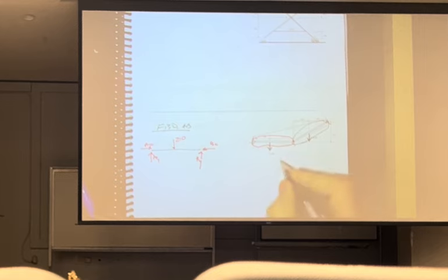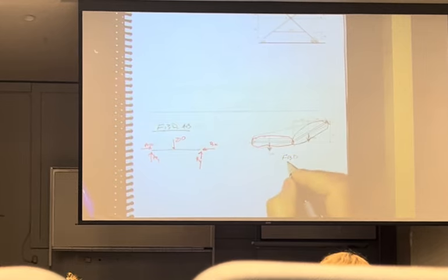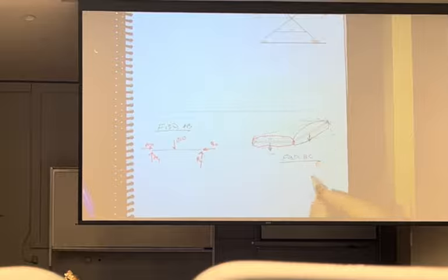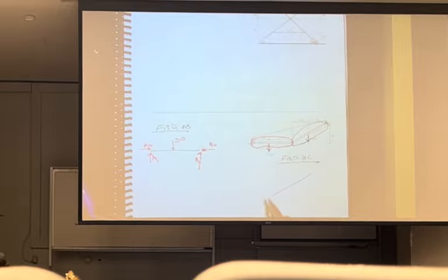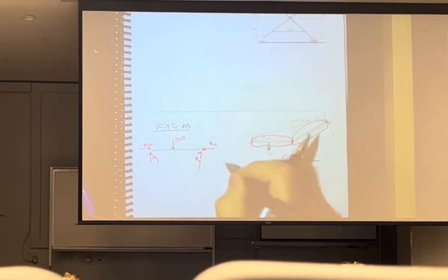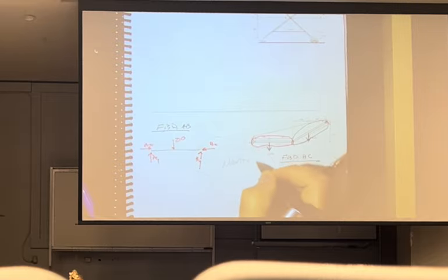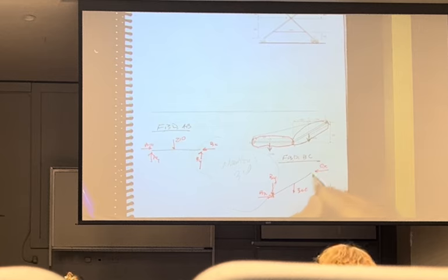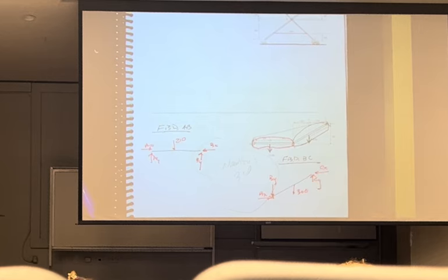The other free body diagram, that is free body diagram of BC, looks like this. I should have BX this way. I should have BY that way. Again, what did I just do? I basically did Newton's third law again. Over here I will have my 300, and then of course I have my CX and CY.